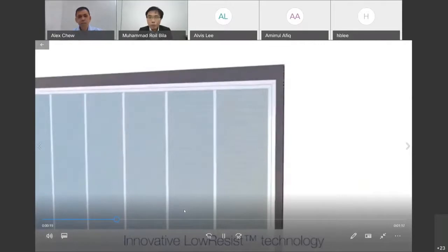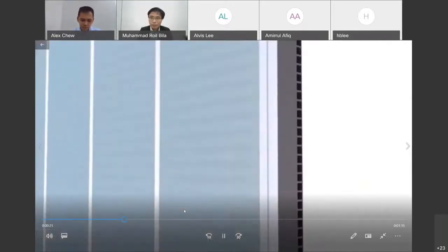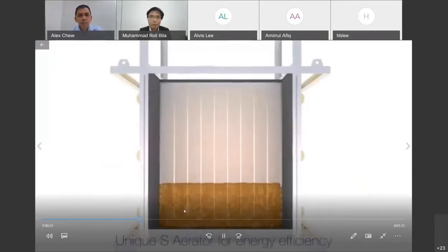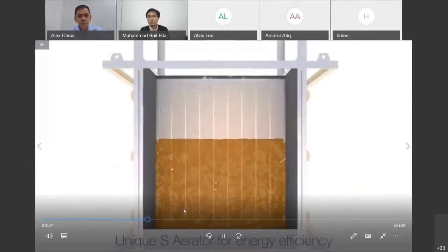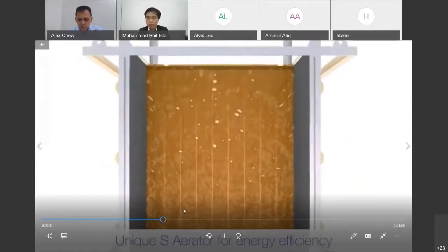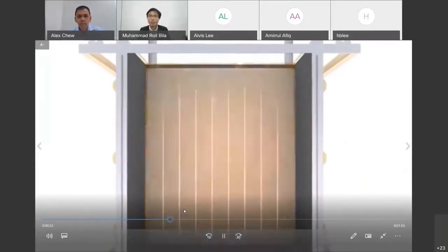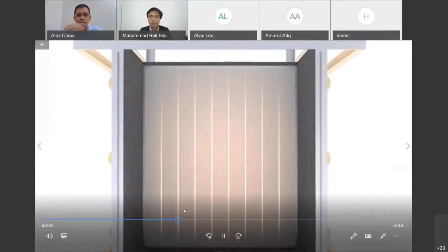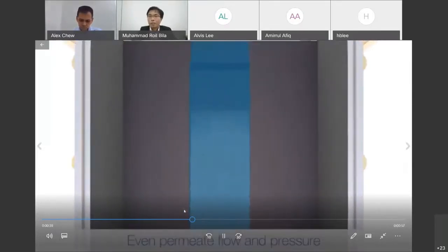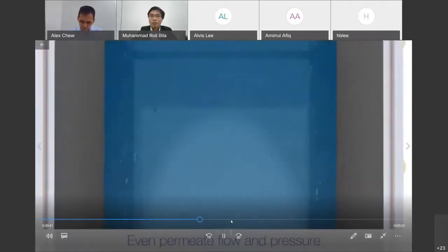They can operate a membrane system fully driven by gravity. So basically, they don't need the permeate pump to take out the treated water from the membrane, from the biological tank. It just uses a simple hydrostatic pressure. As such, it also minimizes the energy consumption of the MBR.